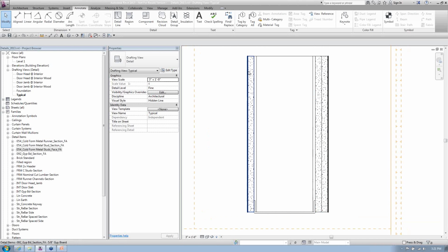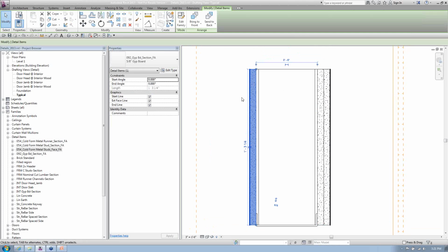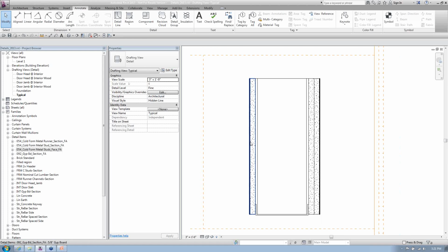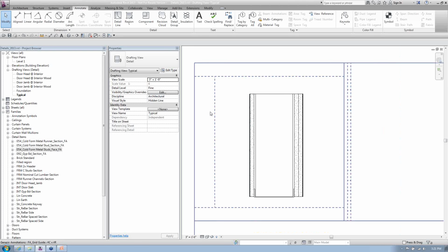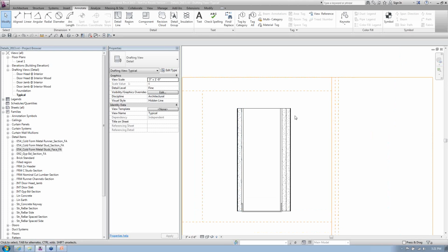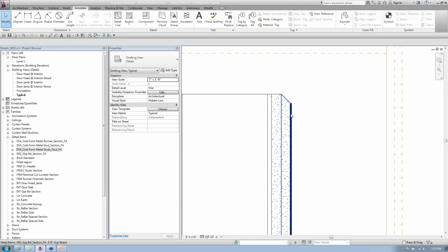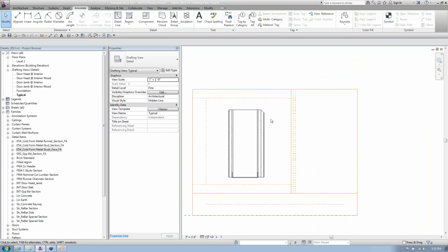Another thing that I've always liked to add inside of here is the fact that all of my detail components, because maybe we wanted to show this is, I just made up my mind what I'm detailing. This is going to be an inside corner detail or something like that. So I've got this inside corner here. So I give myself the capability to allow any of these to have an angle on them. So I can come over here to the inside and say, hey, give me a 45. If it goes the wrong direction, give myself a negative value inside of there. So it allows me to come through here and really start getting into creating what I needed to do.